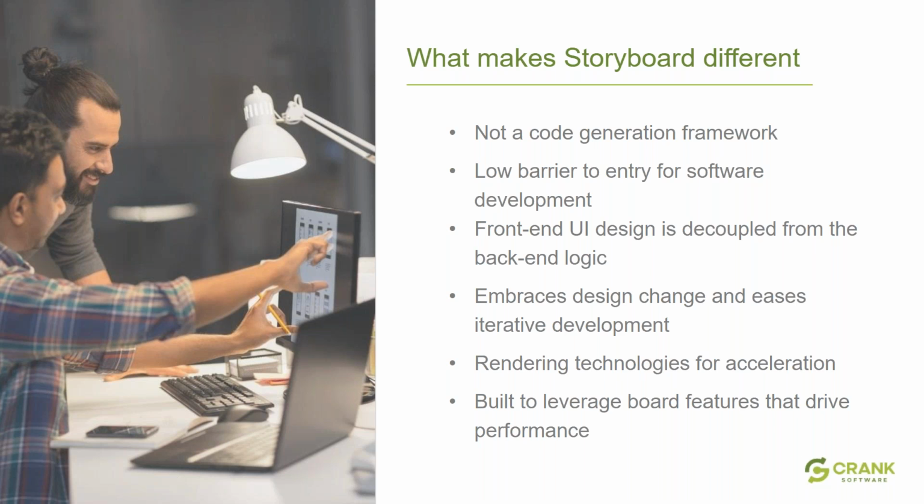So I mentioned earlier, perhaps there is 3D acceleration available on your board. We can leverage OpenGL to help accelerate and offload the CPU. The same thing holds true for some of the lower powered MCU platforms that might be running an M4, M7 core. Some of them have 2D accelerators, and in that case, we can also leverage that to help offload the CPU and accelerate some of the graphics and rendering. All of this is done internally by us. You don't need to worry about that. So again, you just get to focus on building up your UI.